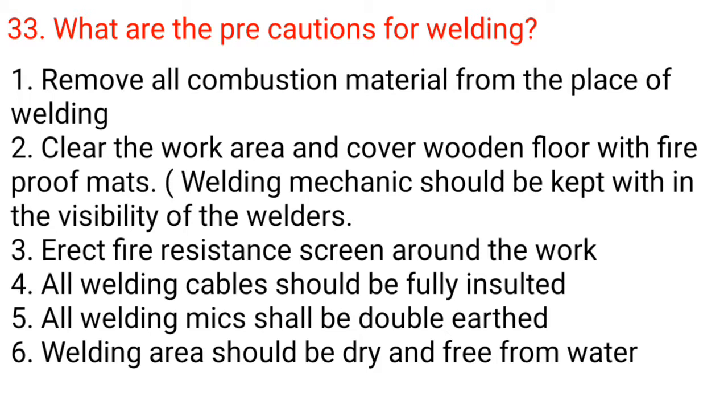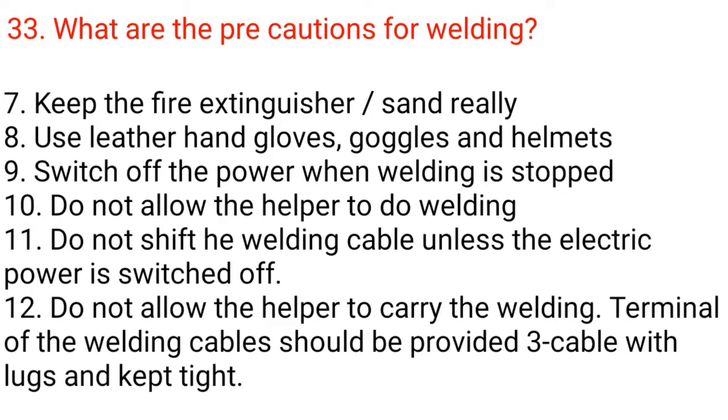6. Welding area should be dry and free from water. 7. Keep the fire extinguisher, sand ready. 8. Use leather hand gloves, goggles and helmets. 9. Switch off the power when welding is stopped. 10. Do not allow the helper to do welding. 11. Do not shift the welding cable unless the electric power is switched off. 12. Do not allow the helper to carry the welding.